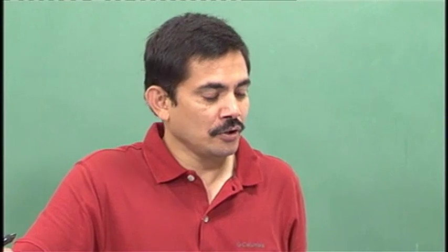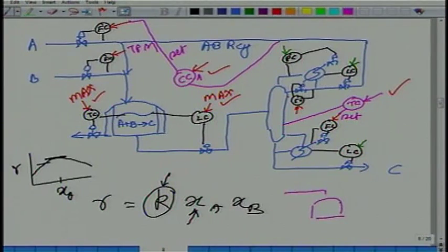Why not the 2 flow controllers initially only with the same value of set point? Because then it doesn't guarantee. It's like the tank problem. Same thing. I discussed this with you maybe in the first lecture. You're trying to set 2 independent flows when you can't.